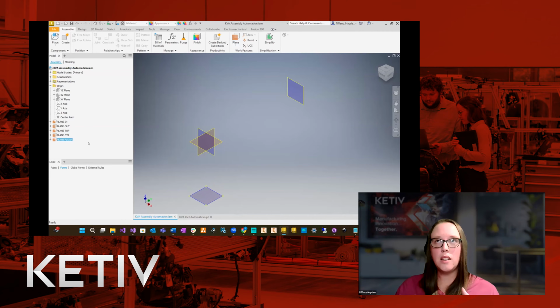So in a lot of ways, if you're dealing with equipment that's going maybe in a building, let's say, you want to mark where that floor is, because the floor can change. Sometimes you're going on a floor, sometimes you're going on a mezzanine, sometimes the levels change. So you want to have where that floor is located. So if it does change, your equipment moves with it in your higher level assemblies. So it's good to have a work plane for that.